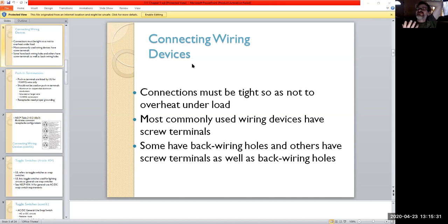Over time, it'll either chew out that wire or chew out that screw, because it's causing little arc flashes, basically flash points in between where it's not bonded all the way. And it creates an amazing amount of heat. So if you go by with an infrared camera, you can see that you don't have a secure connection, or that the device is about to blow.